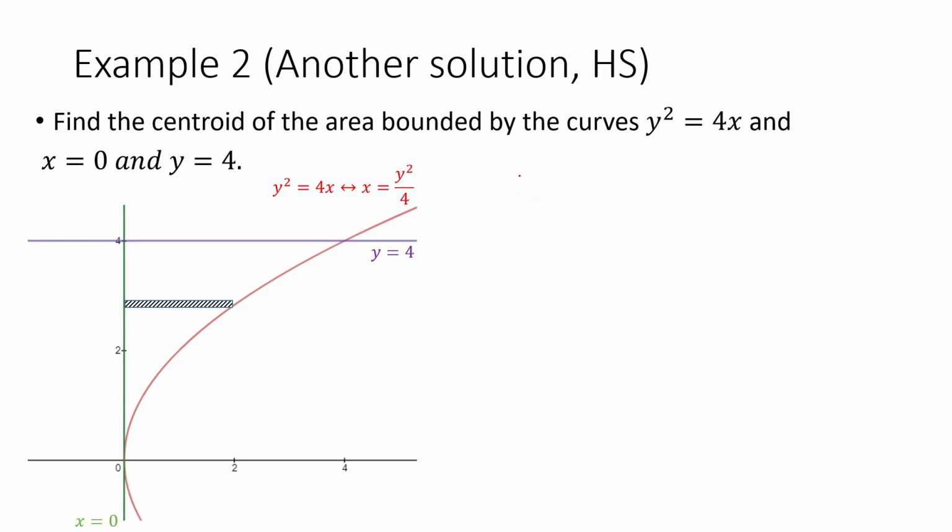Okay, so next we start off first with x bar times area equals x sub c, times the differential area. Again, since we are using the horizontal strip at this point, x sub c times x right minus x left dy, from y1 to y2.